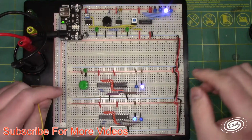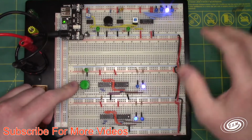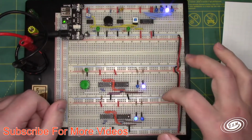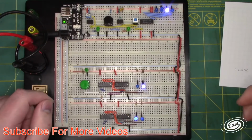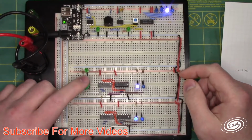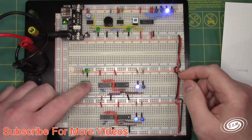Let's look at this one here. This one is the one with NAND gates. It's all hooked up. I'm not going to go into the gritty details of how it's hooked up. But if I pulse the switch, sometimes it toggles, sometimes it doesn't. It can be a tad glitchy.